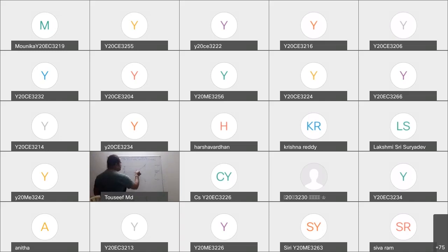Now, if I draw the vertical projector from A dash up to here, this becomes your point A. If I draw a line passing through this point A, this becomes the locus of A. Okay. Now I obtain my AB.